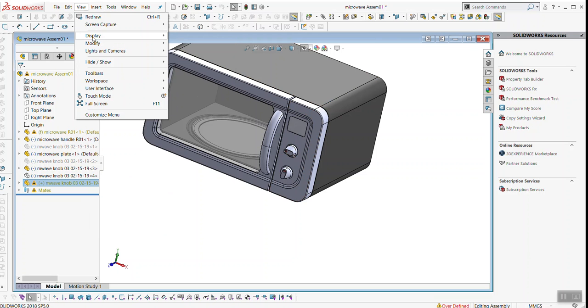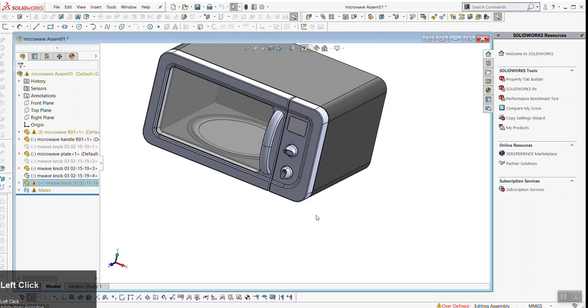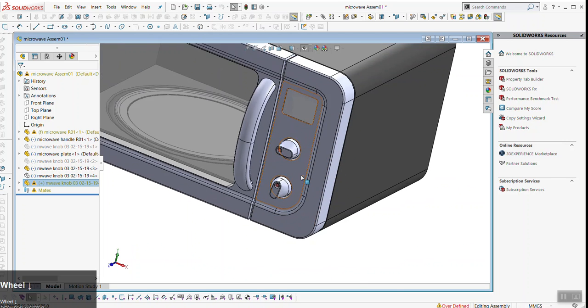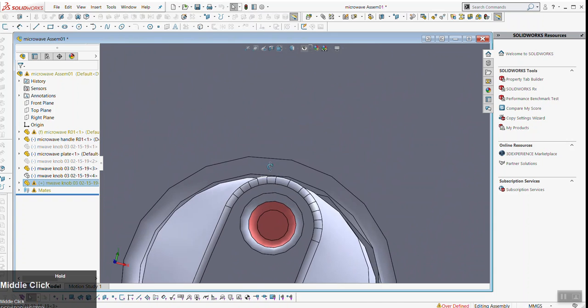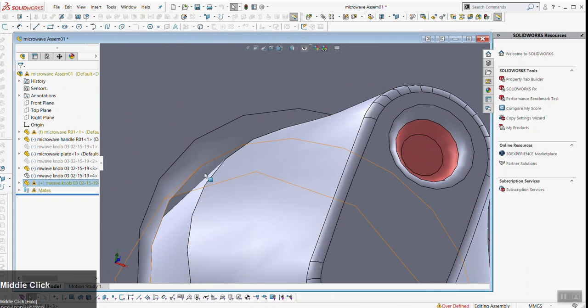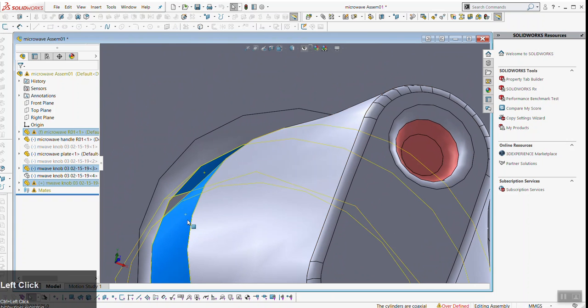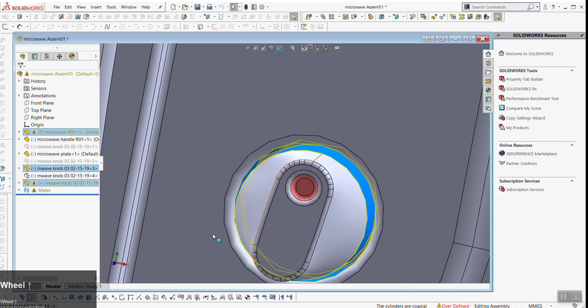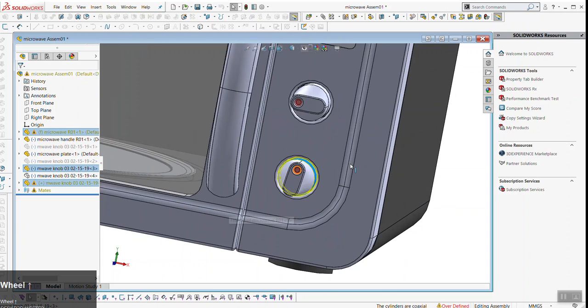If you go to View, sometimes you might have something that you want to spin about a central axis, but you may not have a space for it. For example, there may not be this face here to select or this face here to select. In which case, once again, Mari's trick is really good, because then it still has the flat face and it mates them to center. So I really like that.